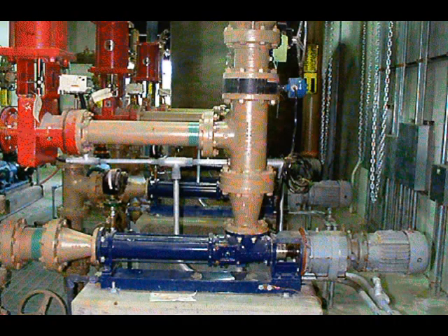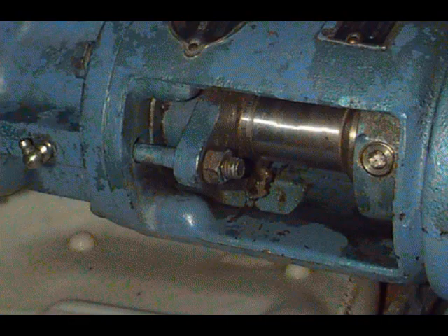In suction lift applications, the suction housing should be filled with water prior to starting the pump. A full pipe sensor may be used to shut off the pump if the suction side is dry. To prevent damage to the pump from dangerous pressure buildups, a similar high-pressure cutoff could be used. The packing gland must be adjusted to allow for a small amount of leakage. Refer to the discussion on centrifugal pumps for information on gland adjustment, packing replacement, and other relevant packing gland information.